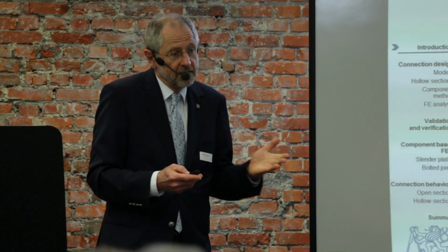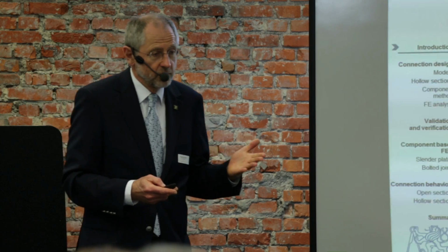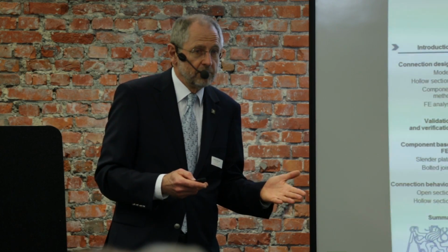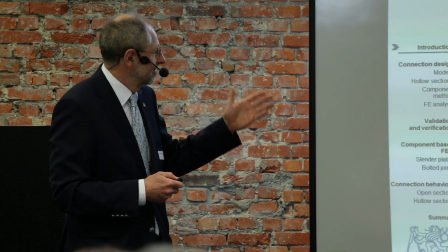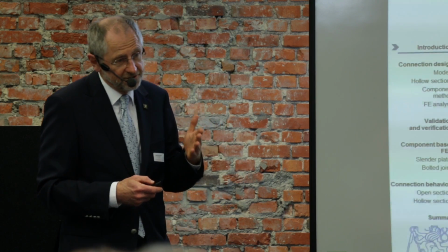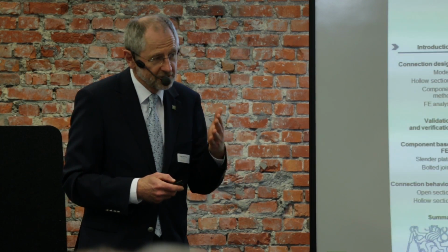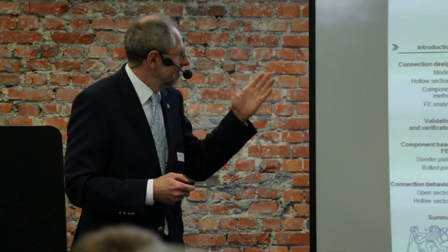And of course, we are trying to avoid brittle fracture, shearing of the bolt. We are trying to have bearing of the bolt. And it's very well known, and this is also one of the reasons that we are using this good engineering, deemed-to-satisfy ideas, because actual yield strength is unknown.